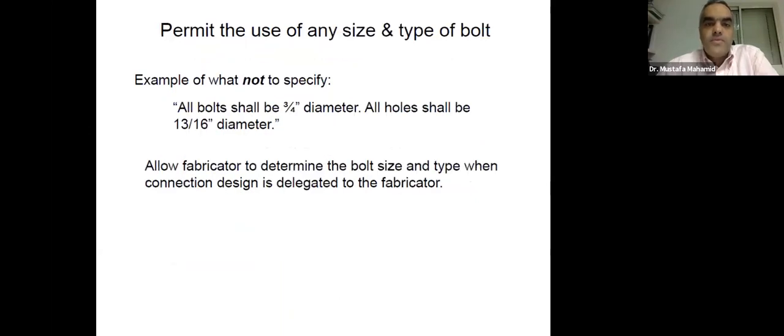Permit the use of any size and type of bolt. Don't restrict the bolt diameter to 3/4 of an inch, as used to be in many in practice. You can use 7/8. You can use 1 inch if needed, and with a larger diameter you may use fewer bolts. If you restrict it to 3/4 of an inch, you end up with a large number of bolts, and you may have an issue of not being able to fit them in the connection. So give yourself some flexibility on that.